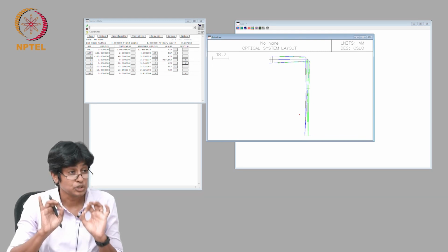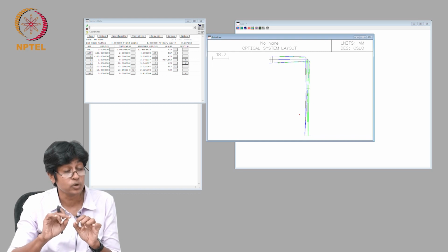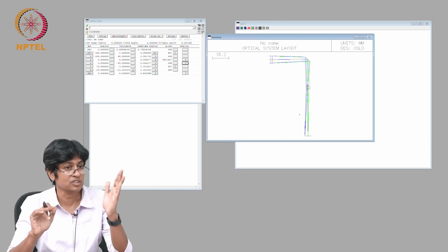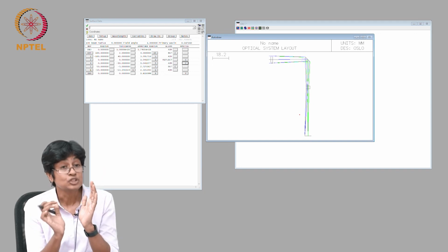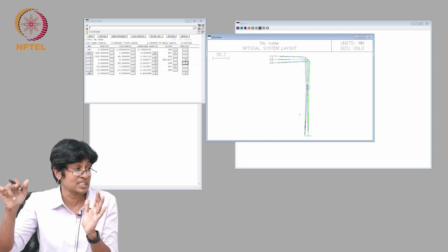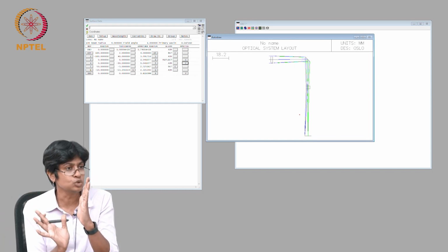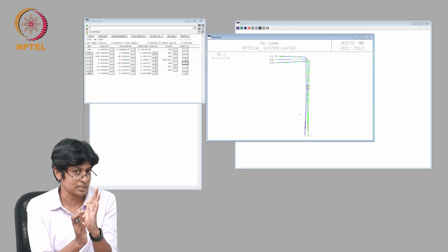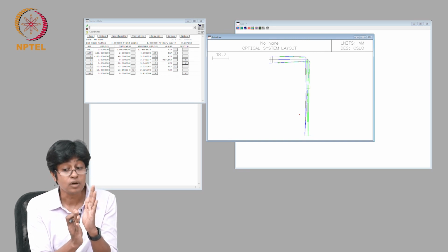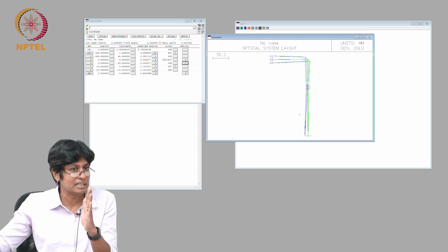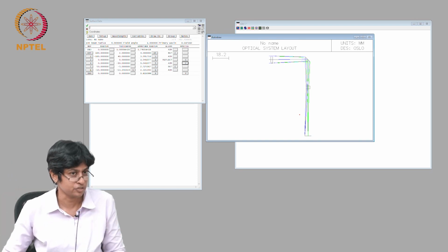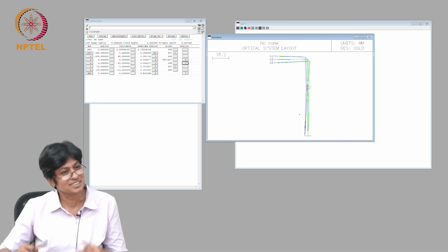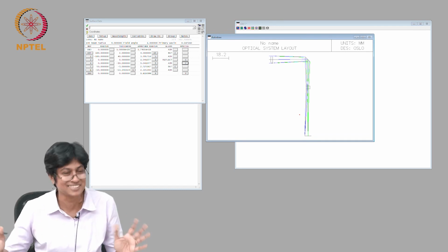Surface 4 should be clear to you now. Surface 4 is linked to the untilted, undisplaced coordinates of surface 3, right? So now if I change surface 3, surface 4 continues to remain linked to the untilted, undisplaced coordinates. Therefore, I can do anything to surface 3 now and it should not affect surface 4. Okay, this is where you have famous last words, and now I will tilt surface 3 and everything will go all over the place. So let's see if it works.